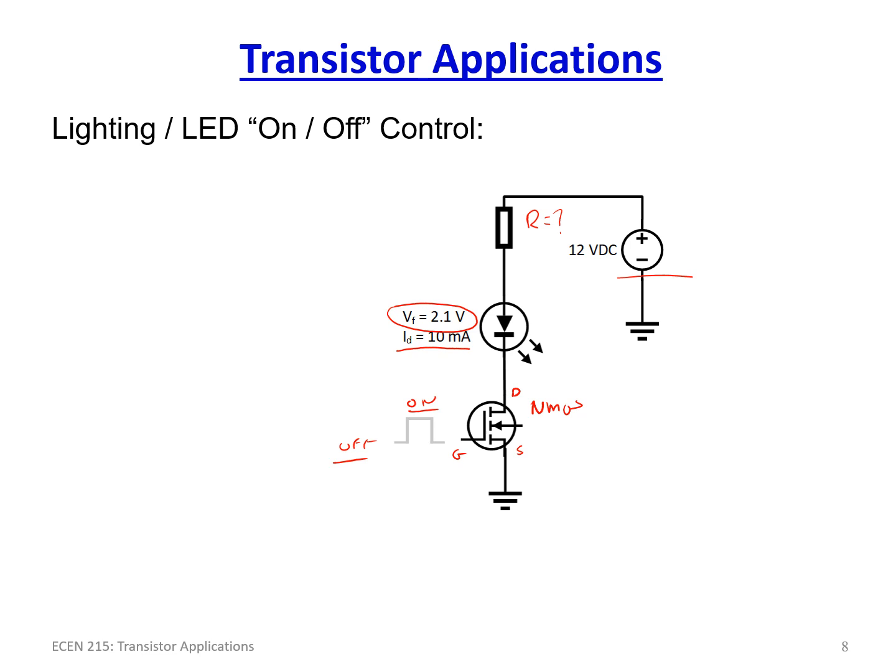So we can solve this simply by going 12 volts minus the forward voltage. So it's the voltage drops here. We've got 12 volts, a voltage drop VR, and then we have our VF. And then the question is, what is the voltage drop across the transistor when it's saturated? Let's call it VTR, which is equal to RDS, the resistance, times ID, which is really small.